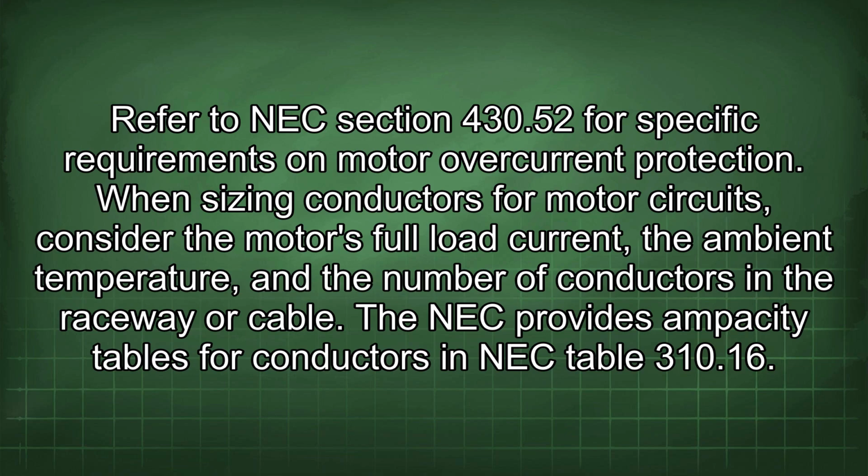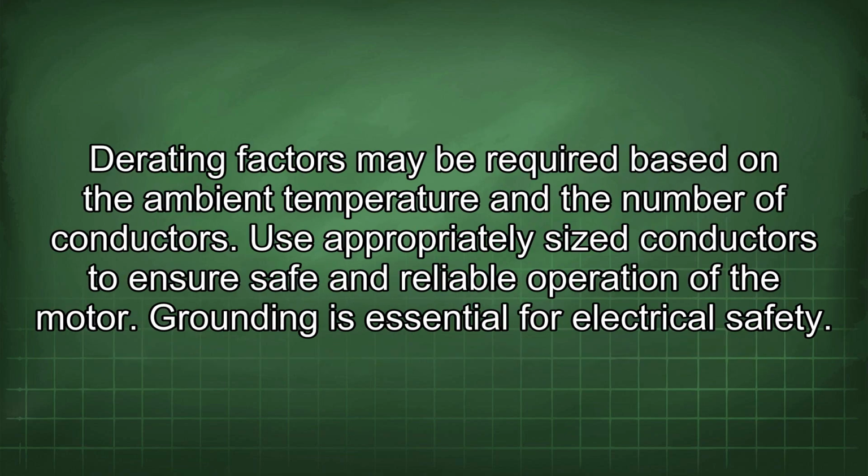When sizing conductors for motor circuits, consider the motor's full load current, the ambient temperature, and the number of conductors in the raceway or cable. The NEC provides ampacity tables for conductors in NEC Table 310.16. Rating factors may be required based on the ambient temperature and the number of conductors. Use appropriately sized conductors to ensure safe and reliable operation of the motor.